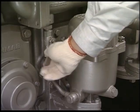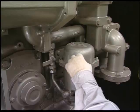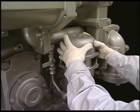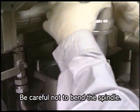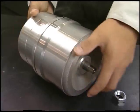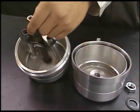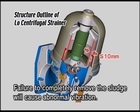First, close the valve on the inlet side of the bypass strainer and remove the tightening nut of the main body cover. Detach the main body cover and remove the rotor assembly inside. Loosen the tightening nut of rotor cover and disassemble the rotor. Remove the sludge on the inside wall of the rotor.